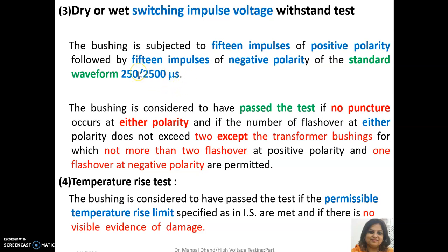Switching surges are more dangerous or severe than the impulse voltage, because even if impulse voltages have huge magnitudes, their duration is very short compared to the switching surge. So the energy transferred through any object or insulating material will be quite high in switching surges. So you have to take care of the protection against switching surges more seriously than against impulse. This is about the protection issue.